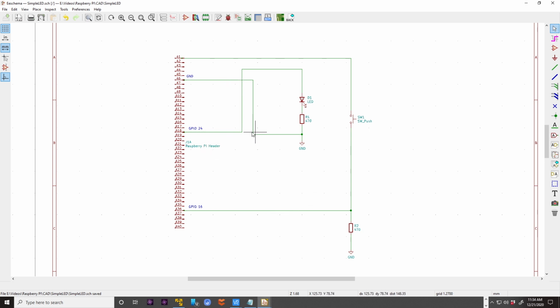All this amounts to here is this one is hooked up to an LED, and when you turn this on, it will forward bias this LED. There's a 470 ohm resistor, which is the closest I had to what I really wanted. I wanted 370 ohms, but I didn't have one, so 470 ohm resistor to ground. It'll forward bias this LED and light it up. Not terribly brightly. The current's limited, but that's okay.